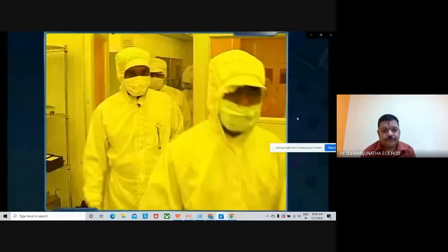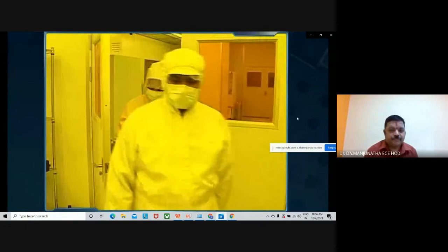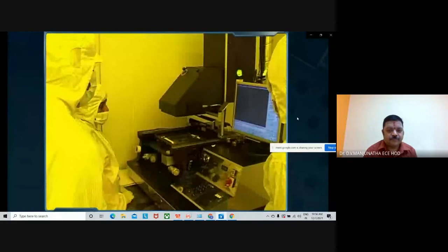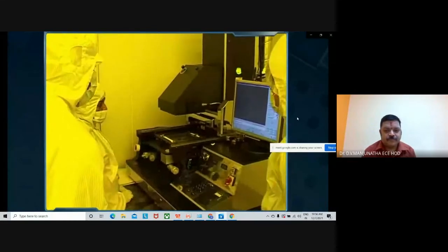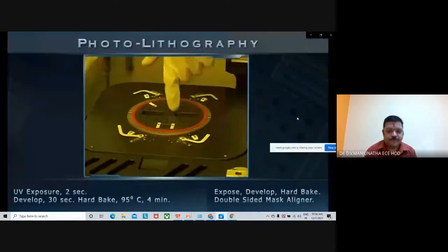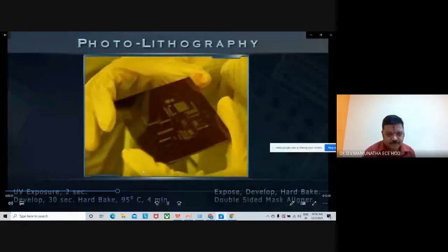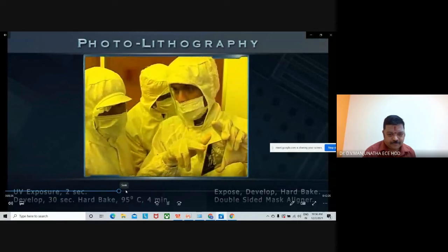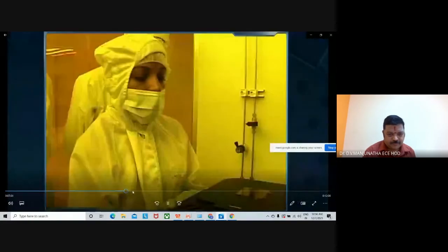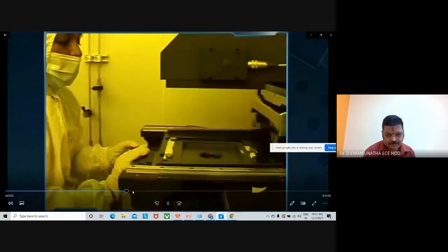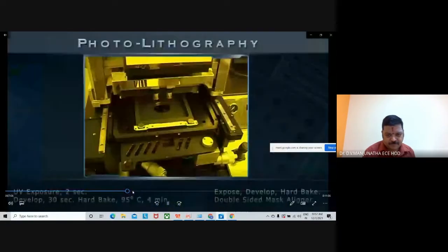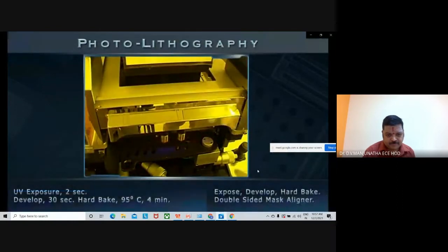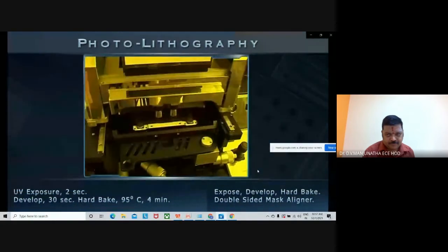We are now ready for cantilever pattern transfer, which takes place on a separate workstation. NNFC has an EVG double-sided mask aligner. First, we pick a cantilever mask prefabricated especially for INUP from our mask library on the wafer. Now the assembly is ready for ultraviolet exposure. UV light exposure is done at predefined energy levels specified in millijoules per centimeter square.